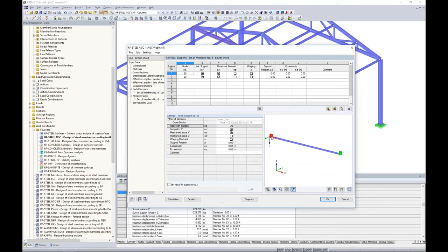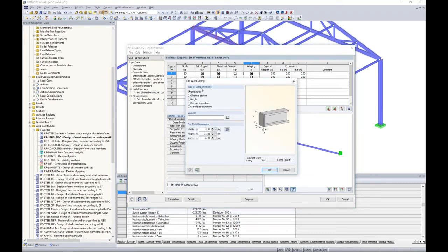It automatically places these supports at either end. Each node along the set of members length has 4 degrees of freedom. The lateral translation, you can see here, we also have some rotational restraint, and we can even take into account warping. For example, if you have warping, we can check this checkbox, go into the details here, and account for warp stiffening such as an end plate.